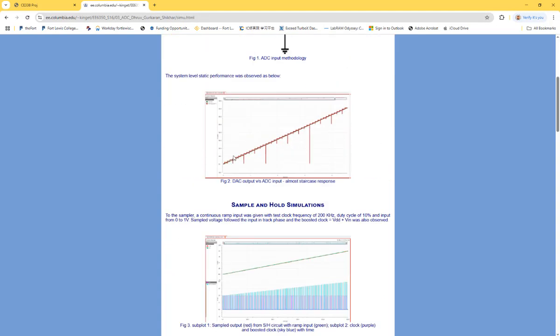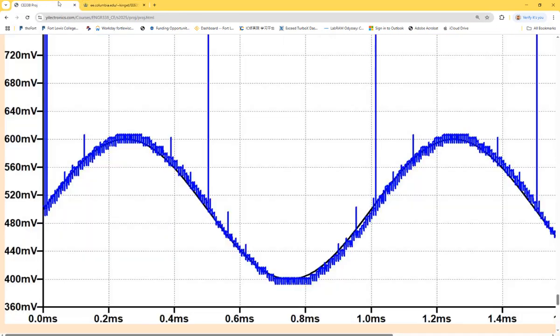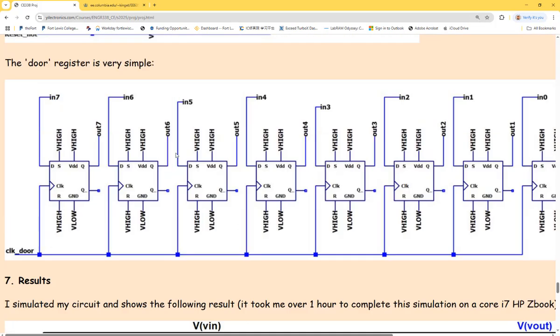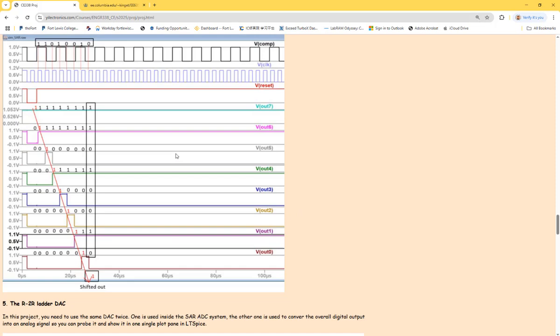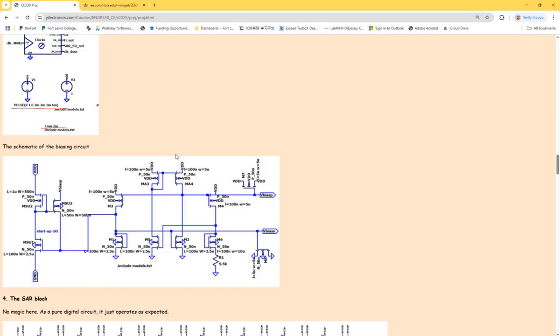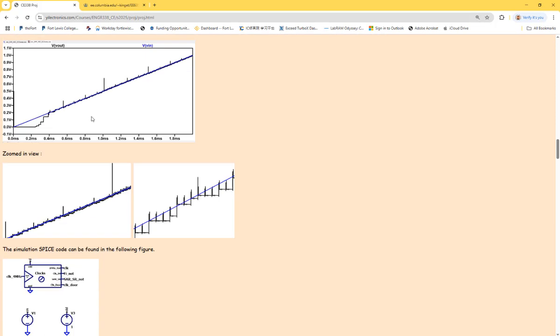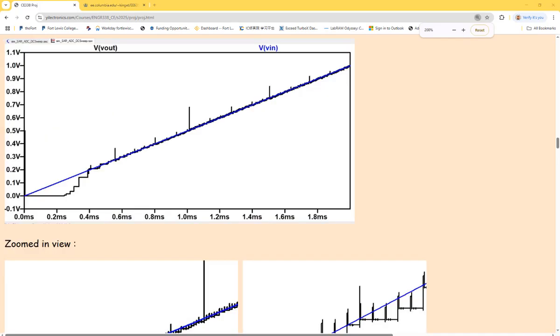of the ADC like this, right? So you want to run a straight line, which is the voltage sweep, and eventually see the outputs. And the outputs have to be the final second DAC's output, because the ADC's output is 8 bits. But eventually this is just one node, right? You can see it's just being probed. It's just one node. So the thing is, can you just simply use the DC sweep to get this curve? So what does DC sweep mean?